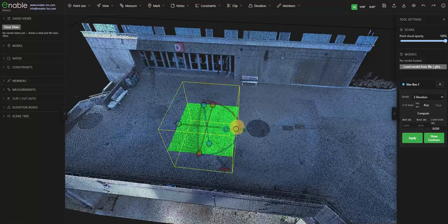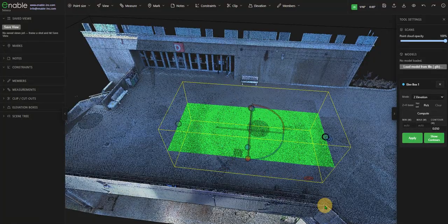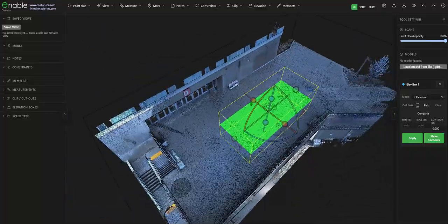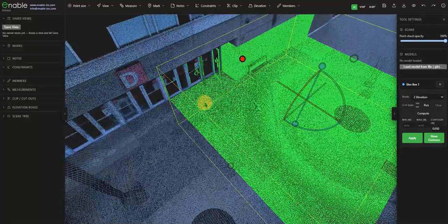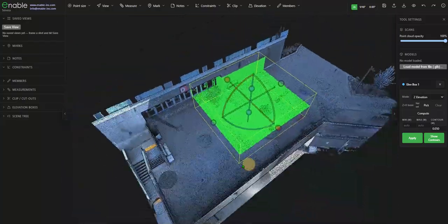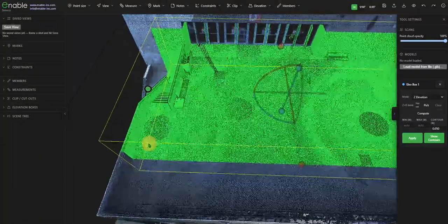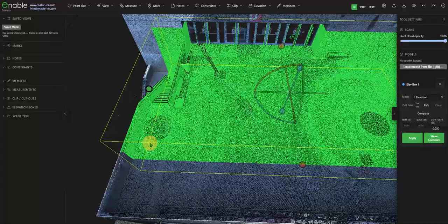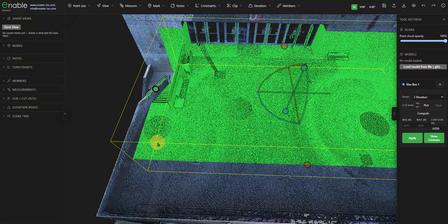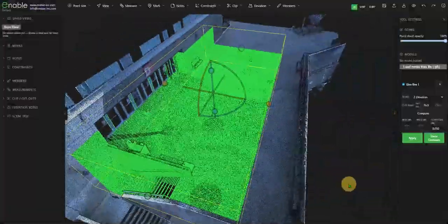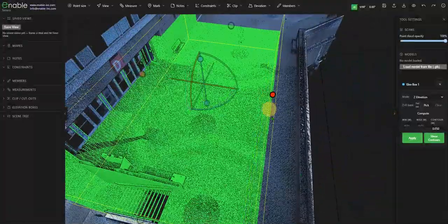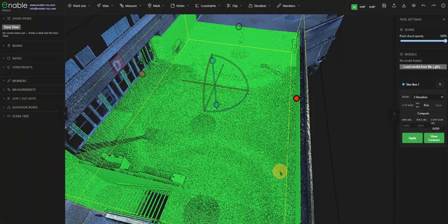So what I'll do is I'll just expand this crop box to include just a few things. I'm going to include all the way up to the building edge and then all the way to this edge. Notice that I'm going a little bit over, and that's okay. I'm just going to pull that back. Just look at when the points start to go up the wall and then bring it back from that. And I'm going to do the same over here. If there's an upturned beam, I don't want to include the face of it because I'm just looking for the slab right now.